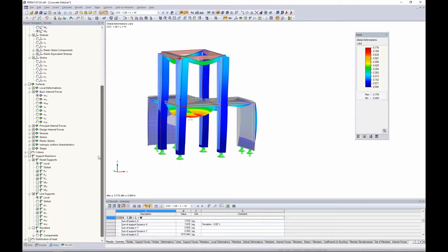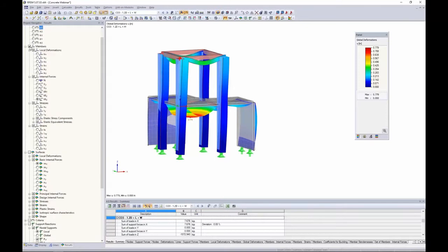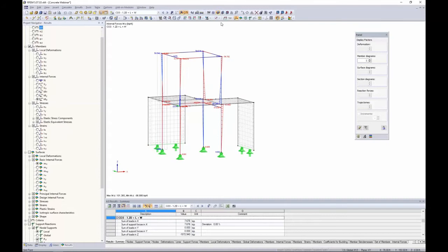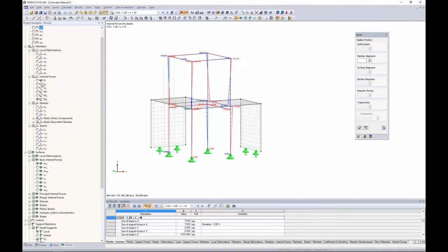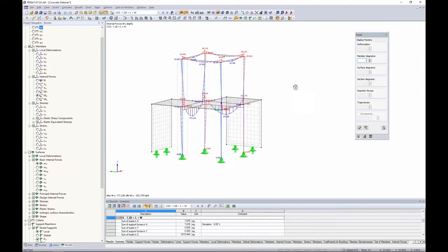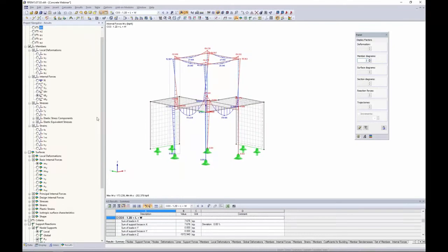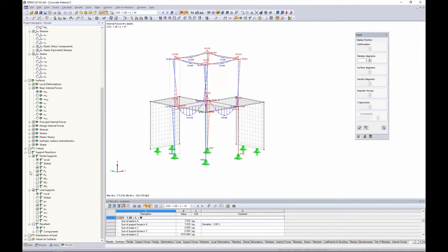So what I was telling you is that in RFEM, you can see that all of these analysis options are available in RFEM alone. Our results tab popped up here. This allows us to maybe view our members, and I can turn this into wireframe mode. Our member internal forces, such as our normal forces for our columns. Maybe we want to take a look at our shear forces. Moments, for example, we can always increase this diagram to make it a little bit more visible here, and you can print this off. So everything according to our analysis is complete.